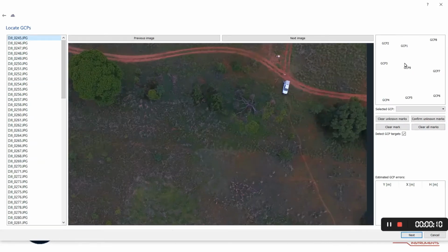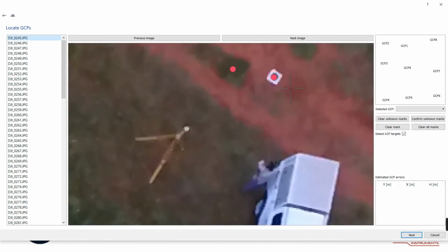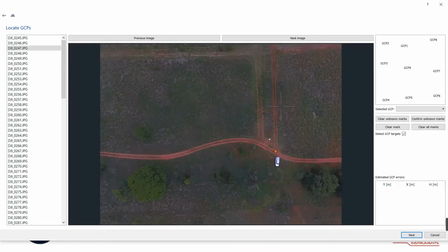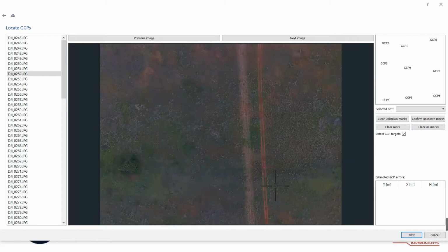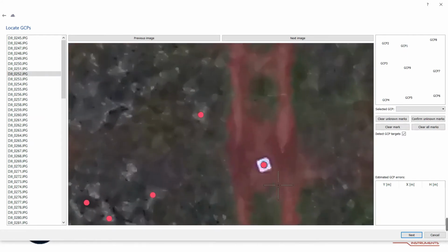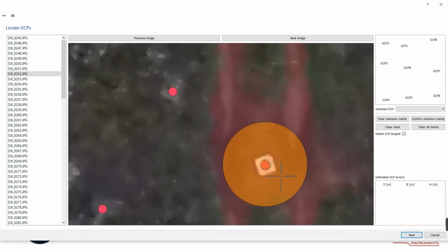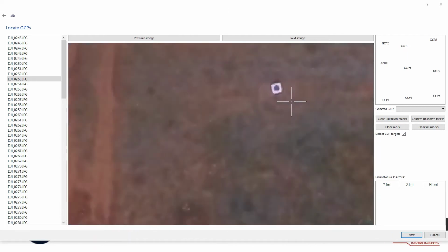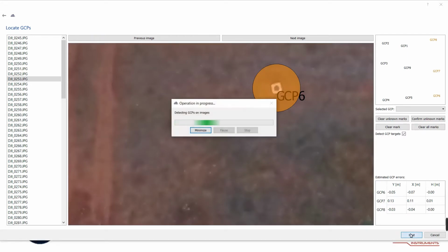So what we'll need to do now is, we've got a small basic map of our GCPs as always, and we'll just select the first one. Alright, and then we'll click on the downwards button to move to our next GCP. You can see it there. Right, and then we can see there's another one. Okay, there it gives a first basic estimate of accuracy. So because you've already selected 3 GCPs, you can click on next.